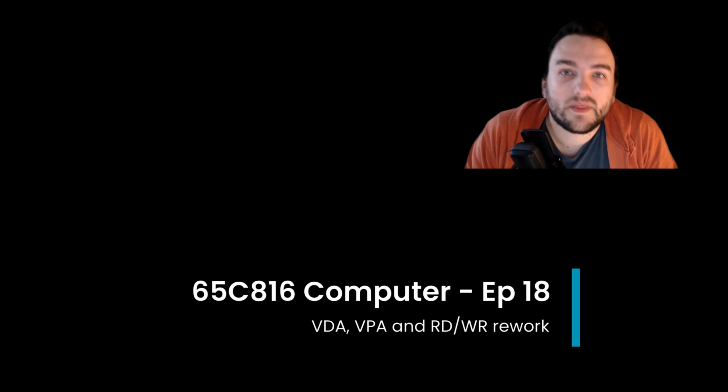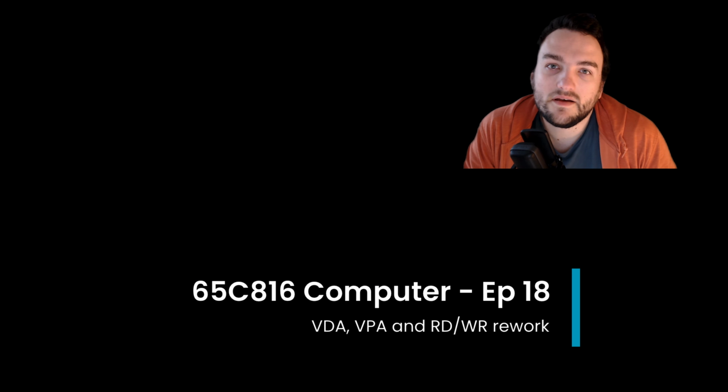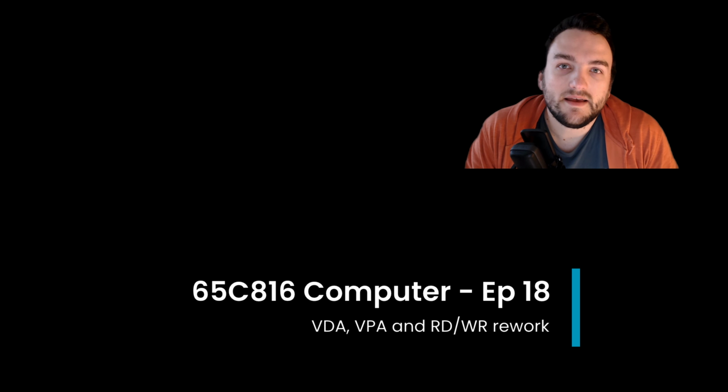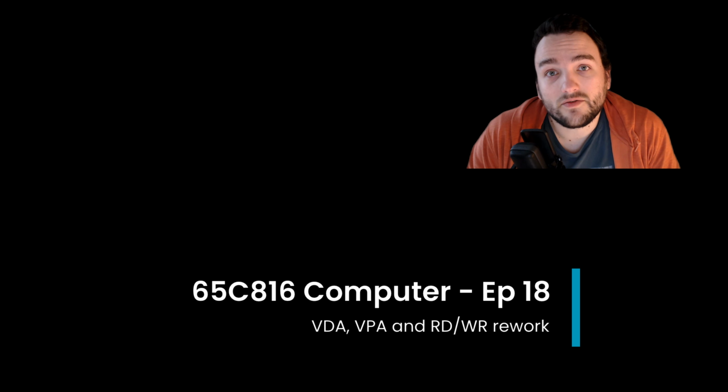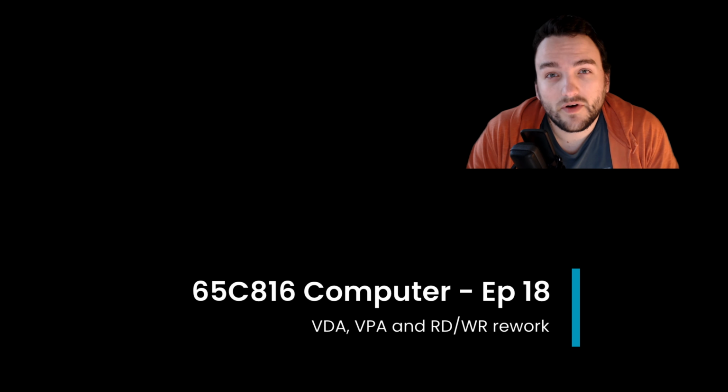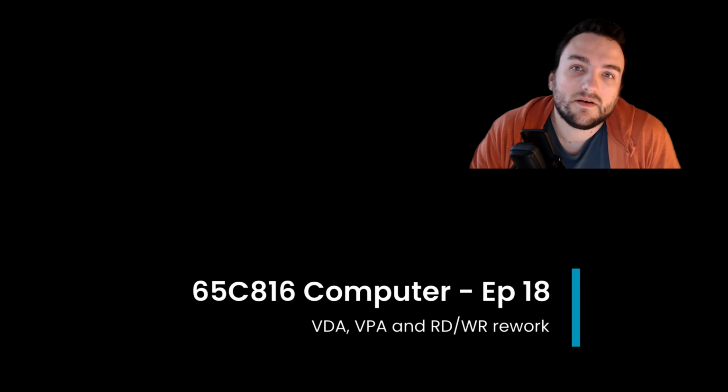Hello everyone! In this video we'll talk about the VDA and the VPA signals of the CPU that qualify bus access, and we'll start reworking our read and write signals to take into account VDA, VPA, ready and bus enable. I hope you enjoy!